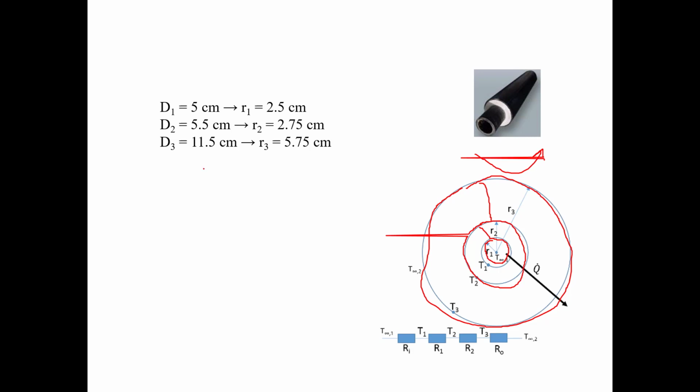Okay, in addition to that, you are also given other heat transfer related data. So you know h1, that is the heat transfer coefficient of the convection inside. You know the conductivities of the iron pipe and of the insulation, and you know the combined heat transfer of radiation and convection for outside the pipe. Okay, so that is exactly what we did in the lecture.